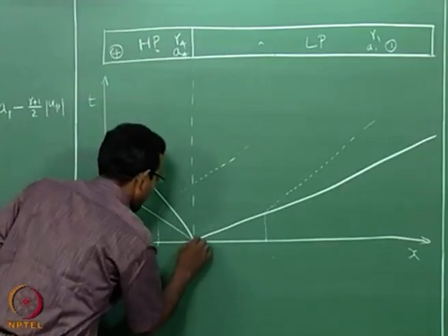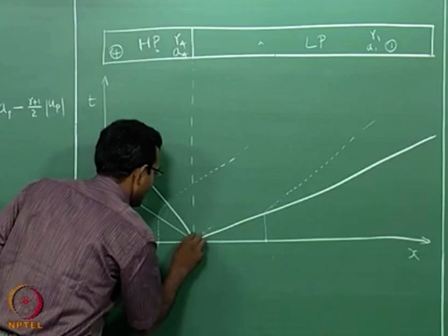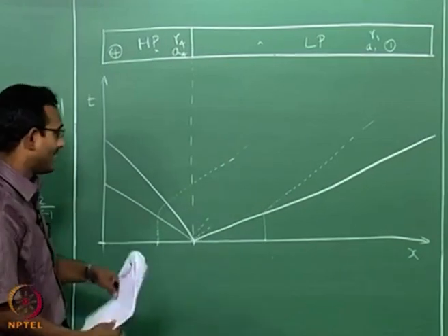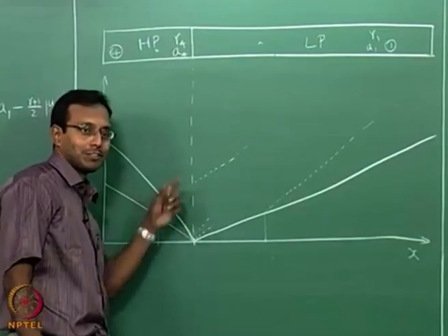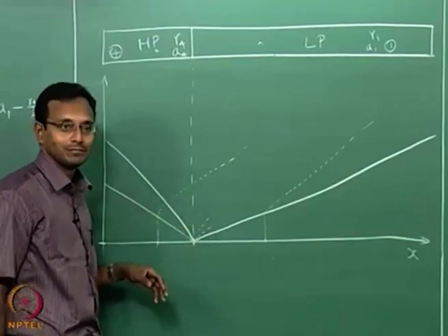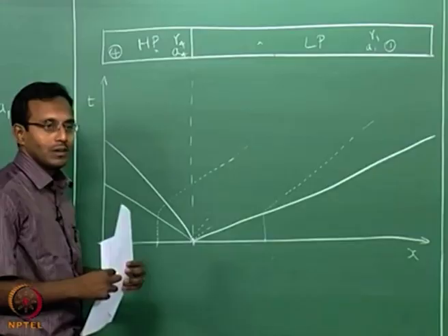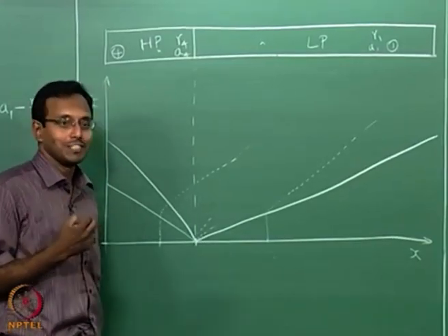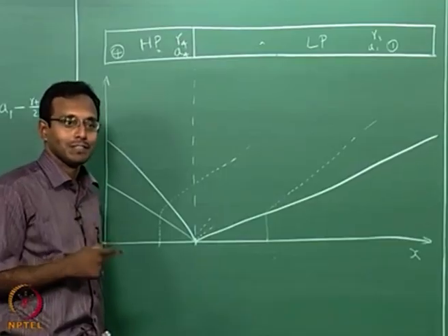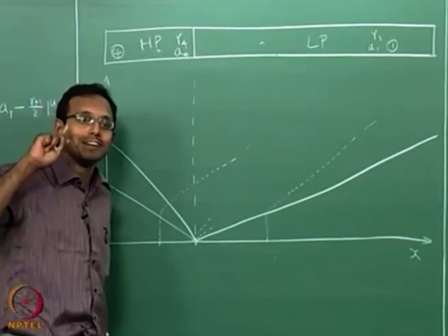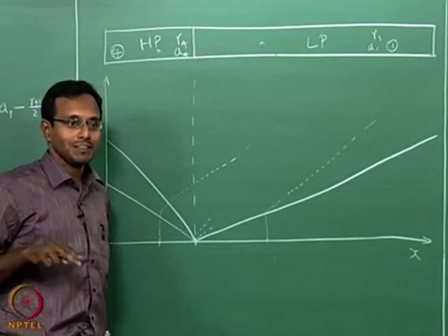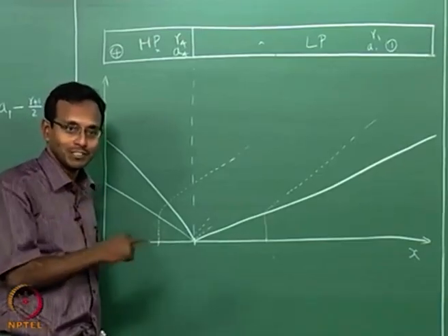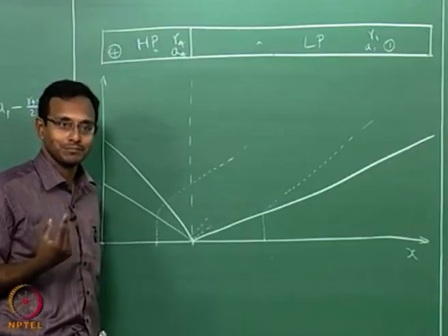Immediately after that, this wants to go this way, while this one wants to turn and go this way. If they are not going parallel, then they will interact and send out extra waves this way or that way to make it equal. Okay. So now I arrived at a particular condition for my flow, which is similar to what we did in 2D gas dynamics. We said the velocity direction should be the same for both the fluids and the pressures must match.